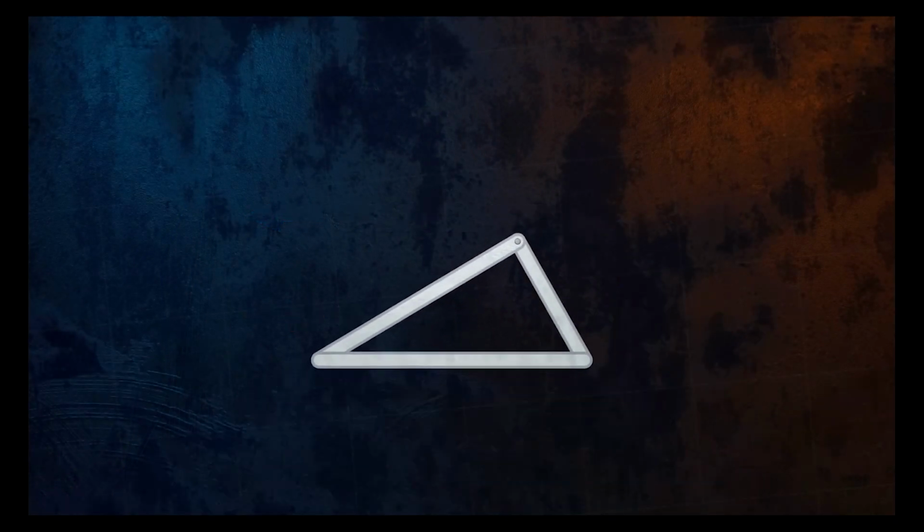The base shape of a truss is three members connected to form a triangle. If a load is applied, the angles of the triangle won't be able to change if the length of each of the members stays the same. This means that the triangle is a very stable shape which doesn't deform when heavy loads are applied to it, making it a great foundation of a large structure.